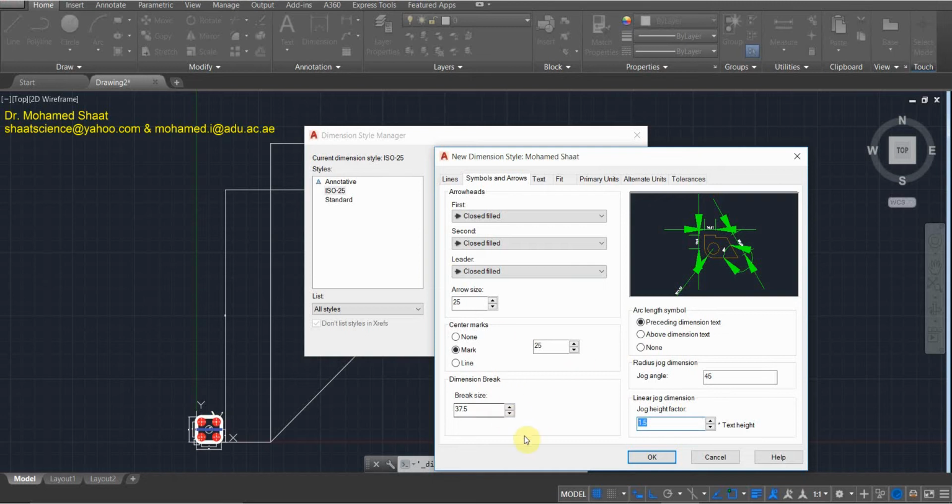Now with these new dimensions, with these new numbers, the arrow will be clearly seen. It's getting bigger in the preview here, right? But as you can see in the preview, the arrow size is too much for the drawing, right? It means that these dimensions are not consistent. Why? Because this is according to the standard, but I do have the object whose dimensions I'm already presenting. It is scaled up. It is too huge in terms of the dimensions. This is for the arrow size.